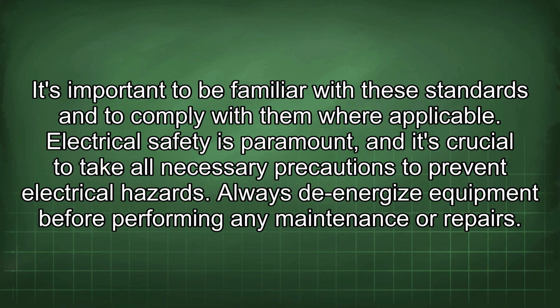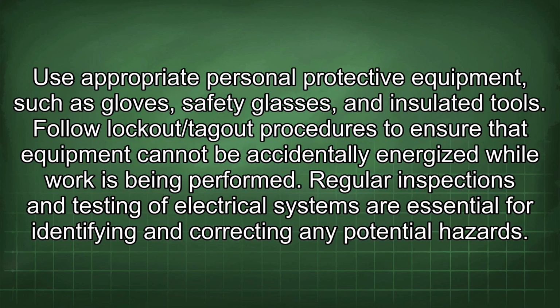Electrical safety is paramount, and it's crucial to take all necessary precautions to prevent electrical hazards. Always de-energize equipment before performing any maintenance or repairs. Use appropriate personal protective equipment such as gloves, safety glasses, and insulated tools. Follow lockout/tagout procedures to ensure that the equipment cannot be accidentally energized while work is being performed.